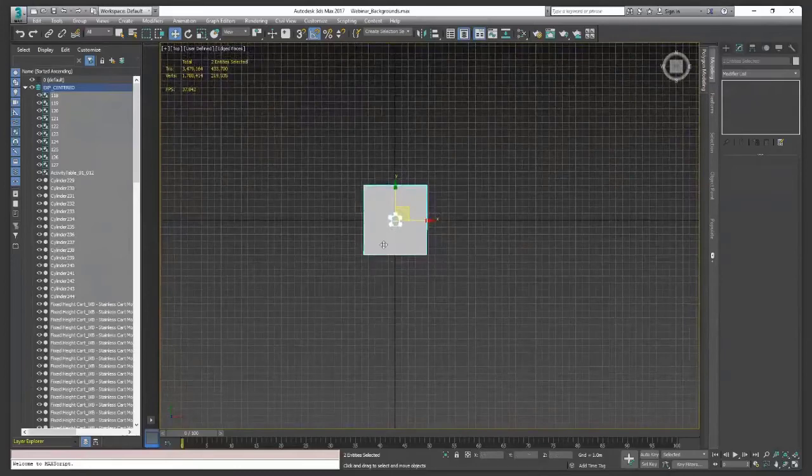Okay, and what happens if we have a very big scene, let's say 2-3 kilometers? Well, the suggestion here is to split it, to create parts and work on each part separately. This is very, very important. This is another best practice to take into account when working with backgrounds, because this way you will be able to update your backgrounds correctly, and you will get the best results with your simulation.